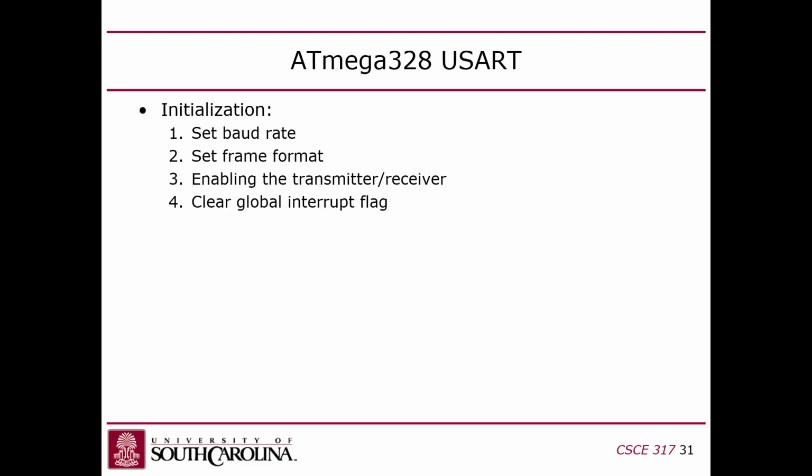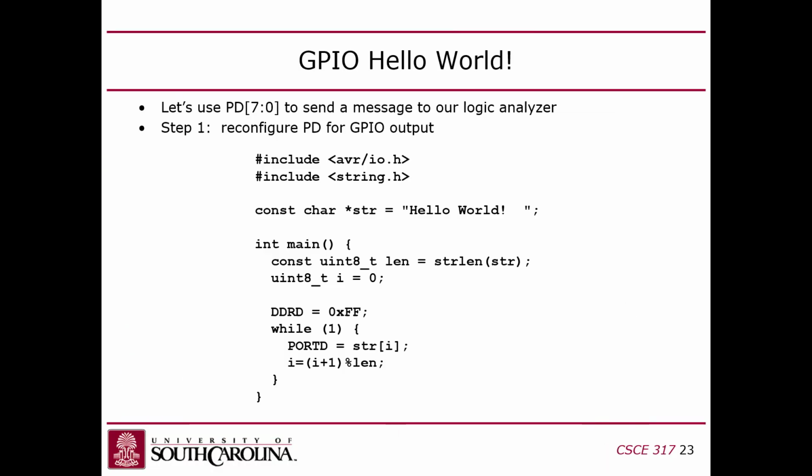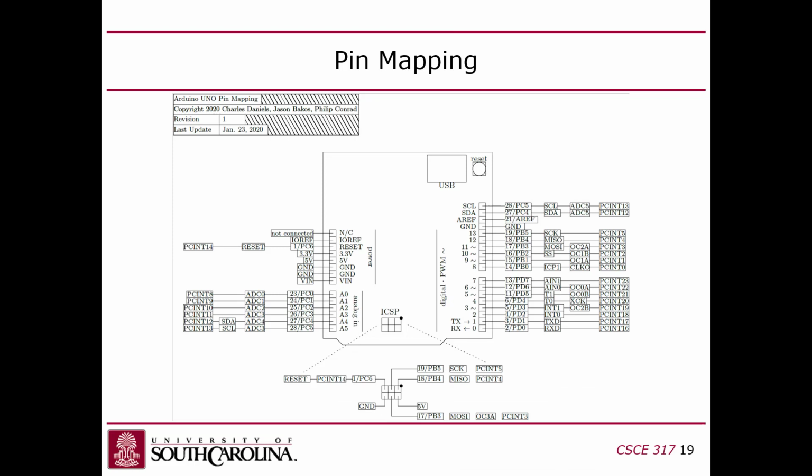If you use the built-in UART, it is going to always use 2 of the pins, which are TXD and RXD, the 2 pins that are in the lower right-hand corner of the board, which also correspond to the 0 and 1 bits of port D. So that obviously means that you cannot simultaneously use all 8 bits of port D, as I did in my example, as well as using the hardware UART, because you'll have a conflict there, right?